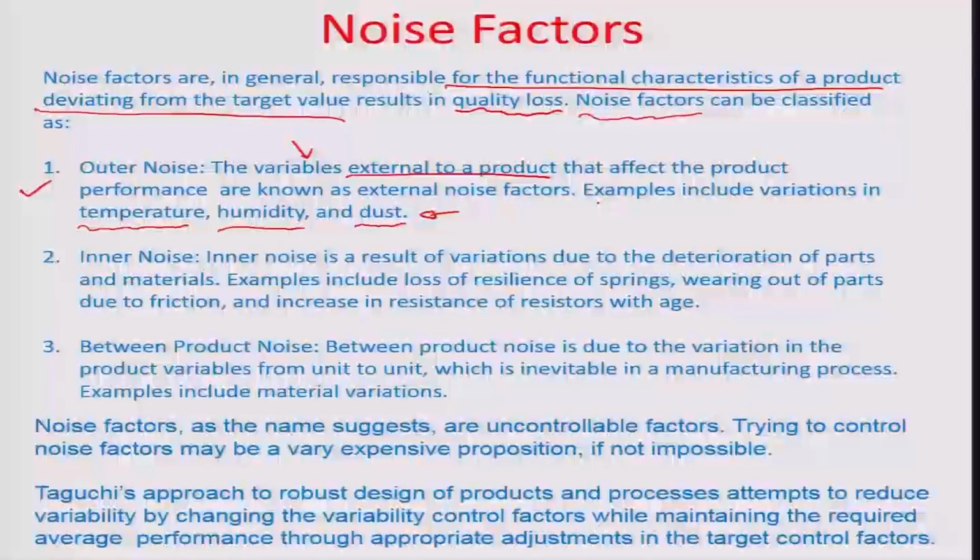Okay, so the temperature in which you're operating your steering mechanism, for example, as laid out earlier, is not in your control. But still there is some noise because of the variability in the film thickness, related to the lubricity that is being provided by the oil in between. So, those are outer noise. Then there is also inner noise.